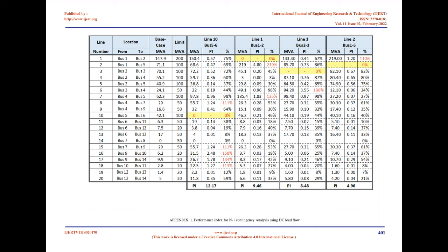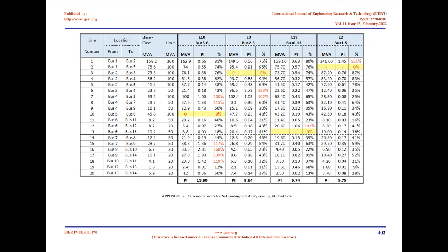Similarly, we can generate the QV for bus 4, a line 1 outage will reduce the voltage tolerance to less than 17% and increase the reactive power injection to keep the system under stable condition with very little dQ/dV equals 2%. Figure 11. QV curves for bus 4 and the highest PI contingency.